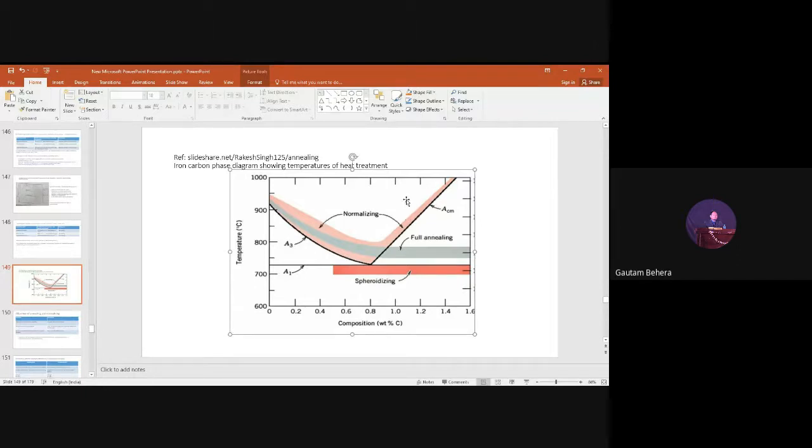If you go to a very high temperature and then cool very slowly because it is annealing, furnace cooling, the time taken for cooling is so high that the cementite will get precipitated along the grain boundaries and spread entirely along them. It forms a network structure of cementite, which brings brittleness into the material. And if a crack initiates, it will easily propagate along the network structure. Finally, the metal will fail. You people have understood now?